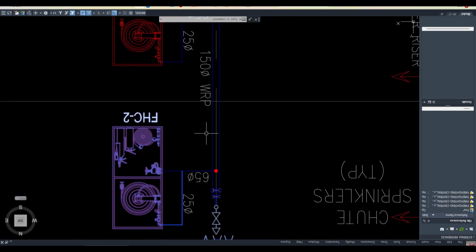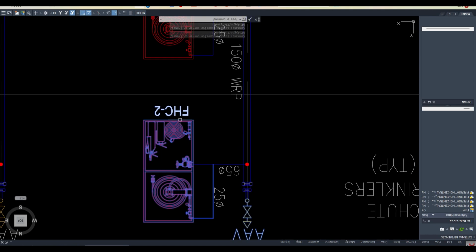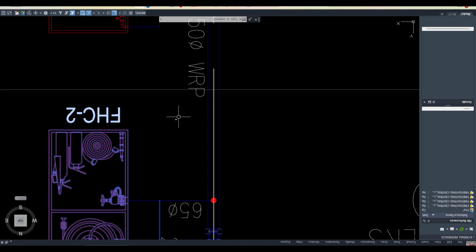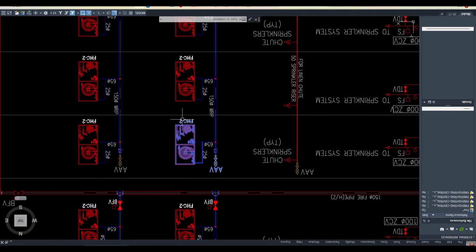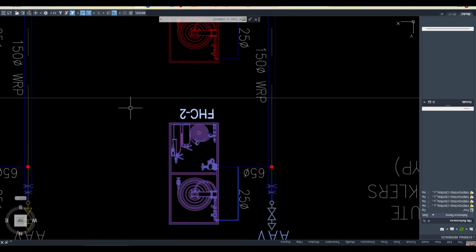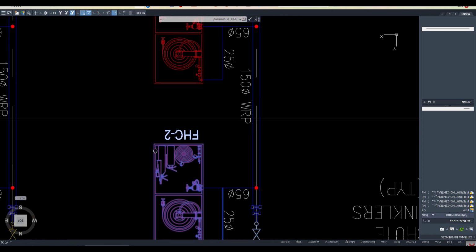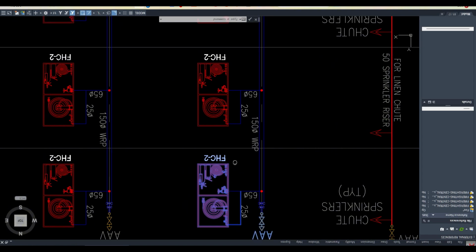What they keep is another pipe here, a drain pipe, which should not be less than 75 mm. Okay, and there is a pipe here, from here they can connect to the stand pipe, like the drain pipe. But here they have not shown that, you can show it in drainage also. Some people, if you have the floor drain, which is meant for the drainage system, in that also you can drain this water. It's not compulsory that you need to have a separate system for that. You have to have a facility where you can drain the water. Okay, so this is that system.